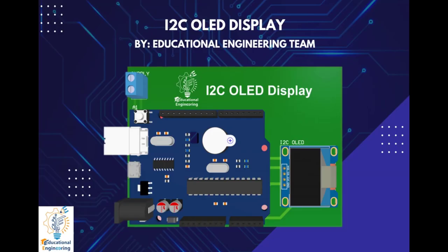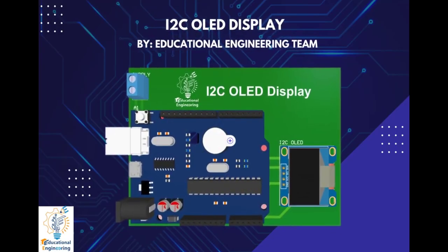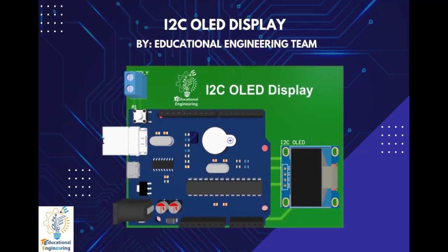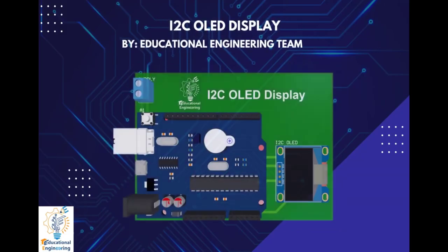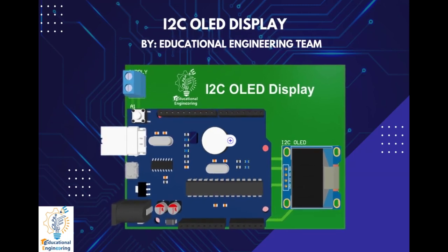For the connection, the SCL pin is connected to A5 and the SDA pin is connected to A4. This video is only a combination of components in one board. You can experience the fully functional device after coding. So now, let's start designing it using Altium Designer.